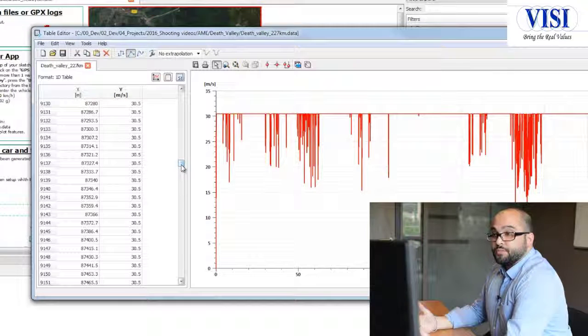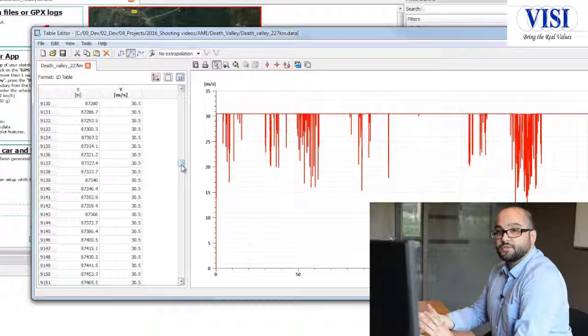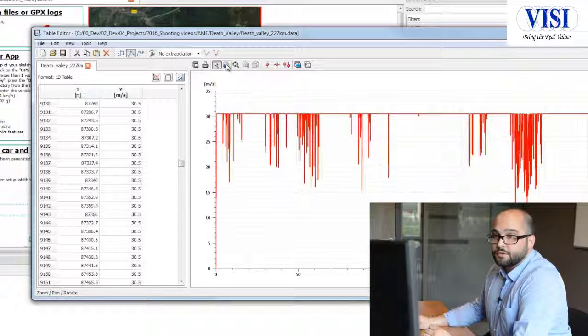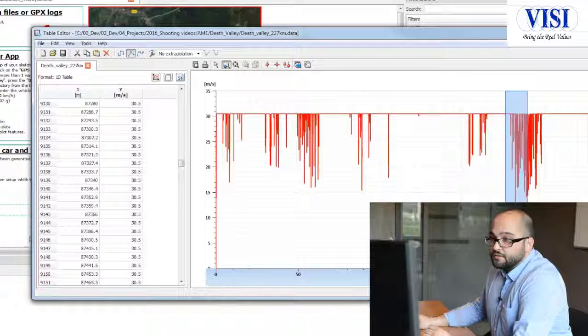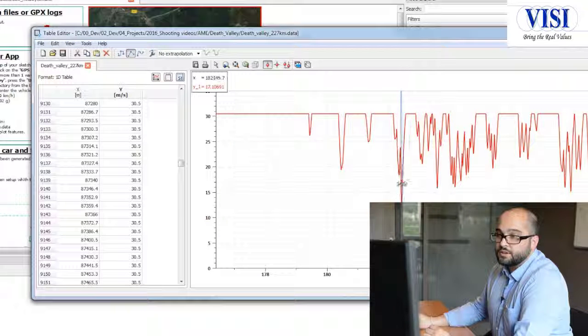Then also an interesting point for real driving emissions is that we need to add some stops, traffic signs, stop signs. So we will choose some points here, for instance, and at this moment we will enter a null vehicle speed to simulate a vehicle stop.